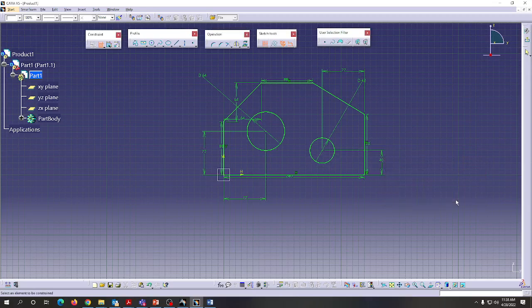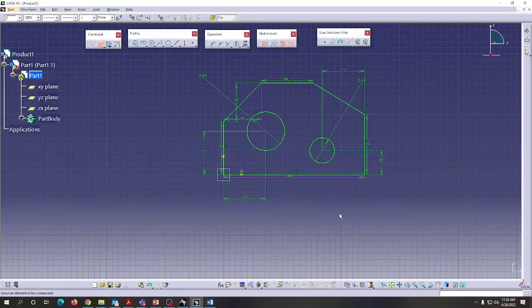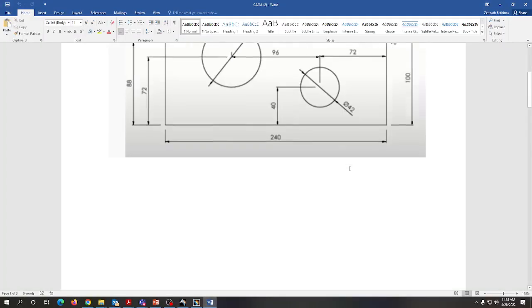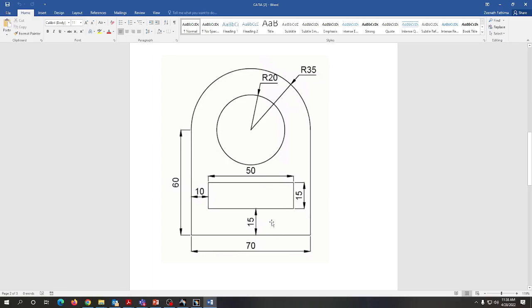So our 2D sketch has got over. Whatever we have got, the simple sketch we have already constructed. The thing here in Catia, whatever the complicated sketch, if you understand clearly with the profile, you can make the rough sketch, you can do all constraints, and you can even fix auto constraint also. But that and all will come only by practice. If you understand the software Catia very well, then it is easy for you to make the sketches. So now we have some idea how to make the sketch. Then we are going to do this simple sketch with circle and rectangle, and here some different constraints also will be there. Some tangential constraint we can make.